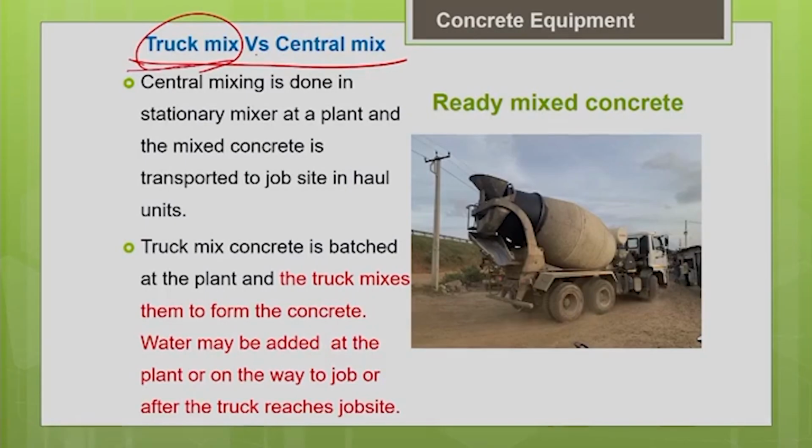That is called truck mix. So generally, when do we go for truck mix? If your job site is located in a remote place, where your RMC transit mixer won't be able to reach the job site within the stipulated time as mentioned by the code, in that case we can go for truck mix.